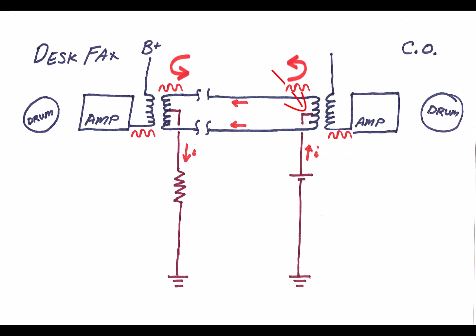Also, since we're injecting that current and sinking the current at the midpoint impedance of the winding, pretty much by definition, half of that current is going to go through each wire in the subscriber loop. At the other end, the two half currents rejoin and come out the other center tap to go through whatever load is connected, and then the current goes to the zero ground connection.